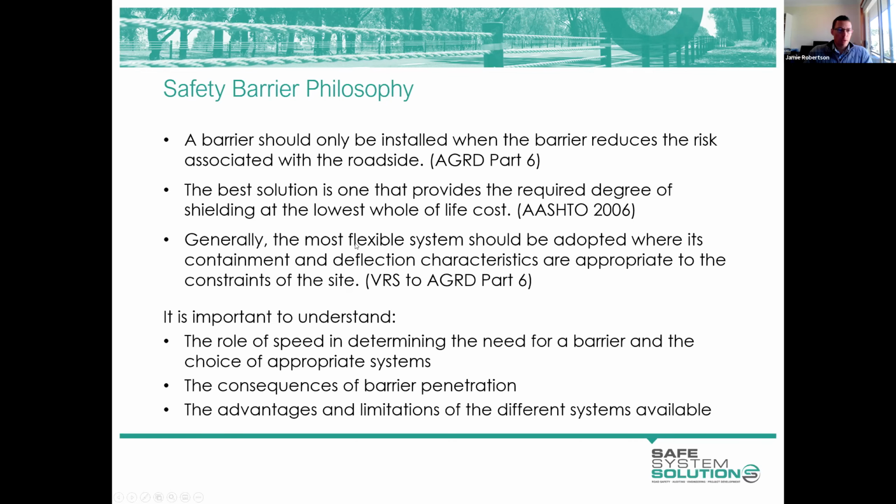And in all of this, we need to keep in mind the speeds that we have at our site and the likely impact angle. Things will affect the impact severity of any crash, perhaps the likelihood of barrier penetration, and that can feed into your choice of system.